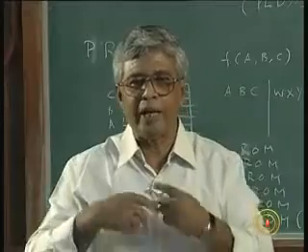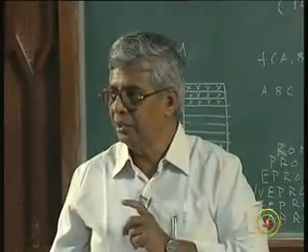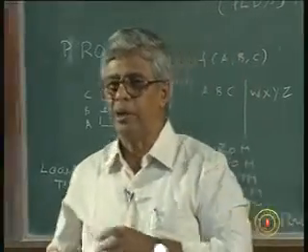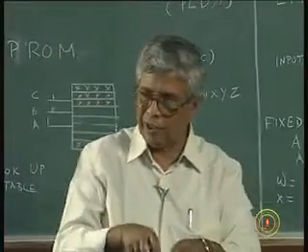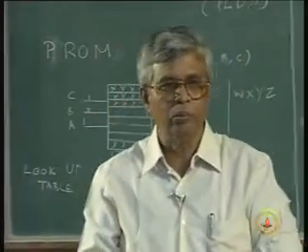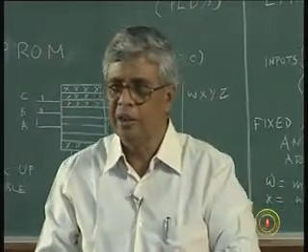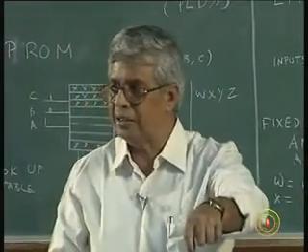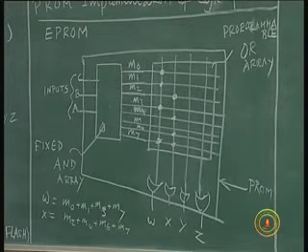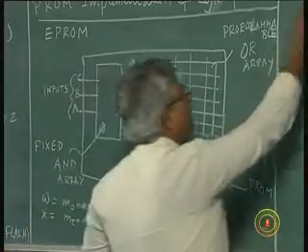Then I go and change my address to 001. There again I will say what is W, what is X, what is Y, what is Z. This is called programming. So I have a little equipment called a PROM programmer, in which I insert this little device, ROM, PROM, and then first type the address and corresponding data into that. So these are called addresses.